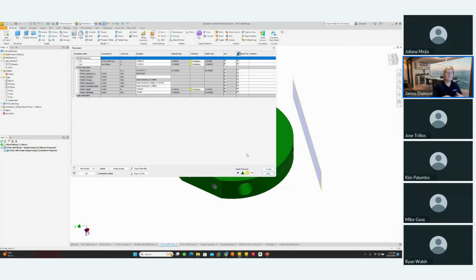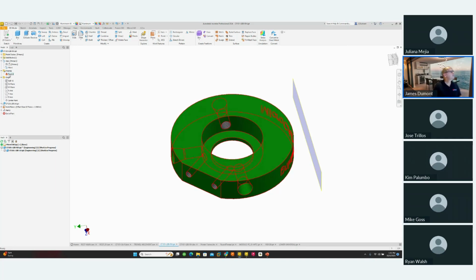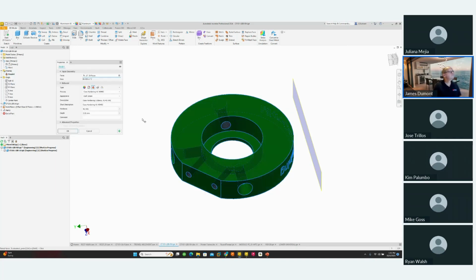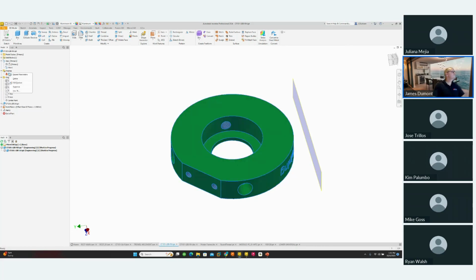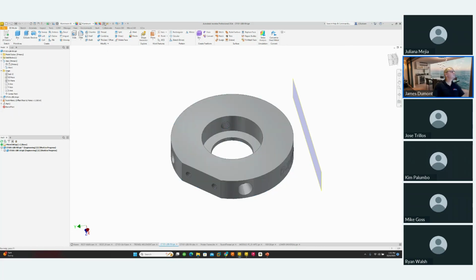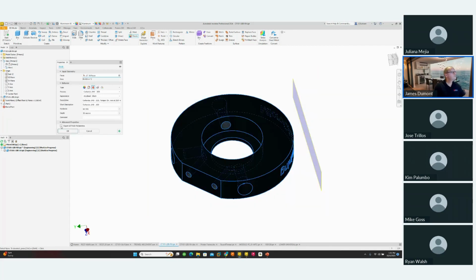So we all know that in Inventor, in order to get access to the parameters, you have to export them. So instead of me coming in here and checking these off, if I edit the finish, it's not going to let me do it now. I thought I did that earlier. Let me delete this. When you do the finish, heat treat, I pick all of the faces. That's what this is. Export all of them to begin with. So all of the parameters that get created will be pushed to user-defined properties, which then can be used.